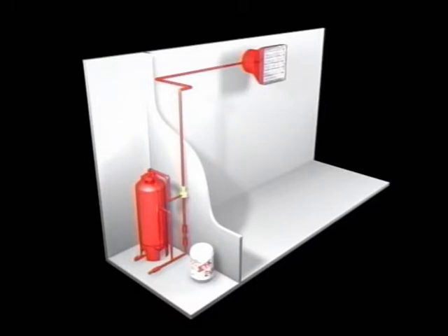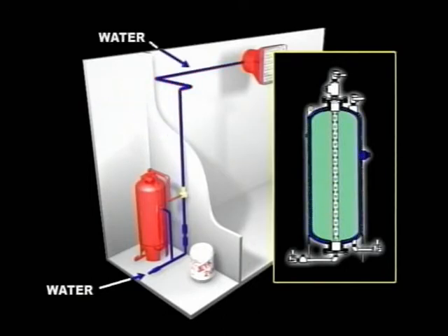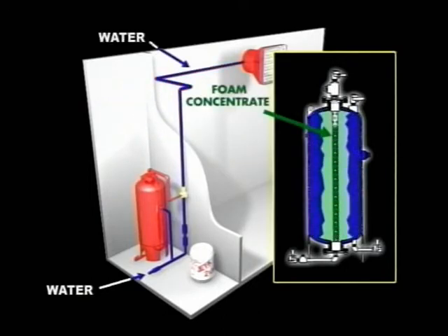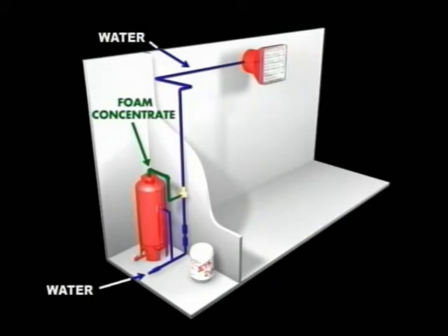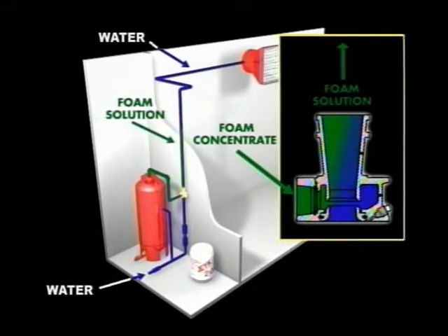The basic system operates solely on water pressure. Water enters the tank inlet where it surrounds the internal bladder. The pressure forces the JetX foam concentrate through perforated tubes to the tank outlet where it's routed to the proportioner. Simultaneously, water is directed to the proportioner at the same pressure as the foam concentrate. The Venturi effect of the proportioner mixes the foam concentrate and water, creating a 2.75% foam solution, or 2.75 gallons of concentrate to 97.25 gallons of water.